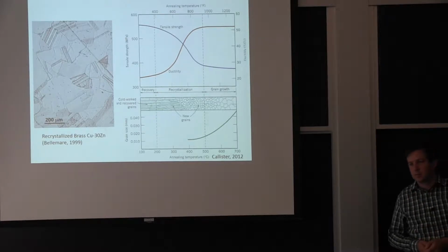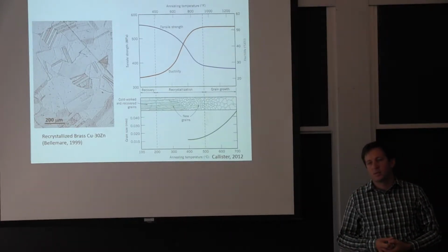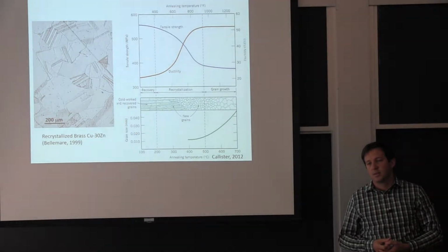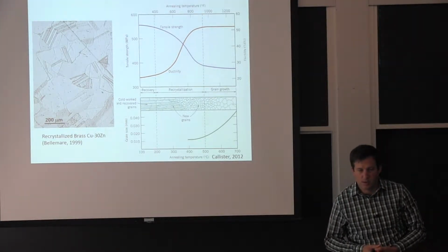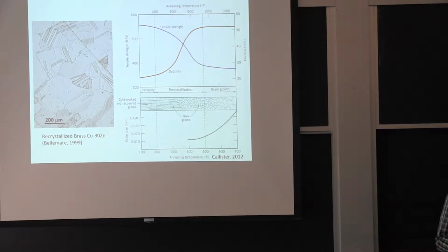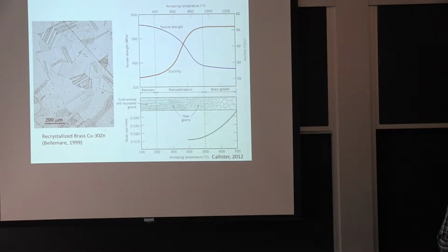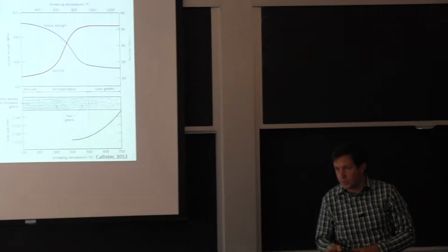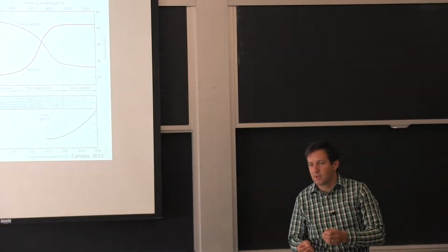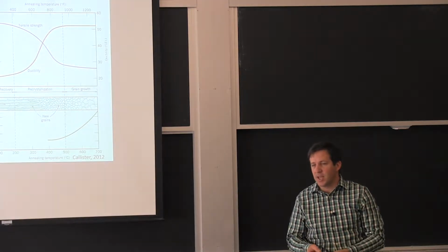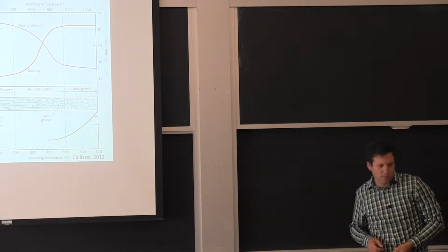Yes? Is it generally the common theme that grain size is smaller during castings compared to, say, extrusions or other processes of forming metals? Okay, so what happens in casting in general is you get bigger grains, especially the dendrites. Each dendrite is more or less a single grain that's growing and keeping a certain orientation that grows very quickly. You do get relatively fine grains in aluminum castings that I've talked about just a little bit at the beginning, because you have two phases. So if you're going to solidify two phases at the same time, a eutectic, and that ties into one of your questions from the end of the class.